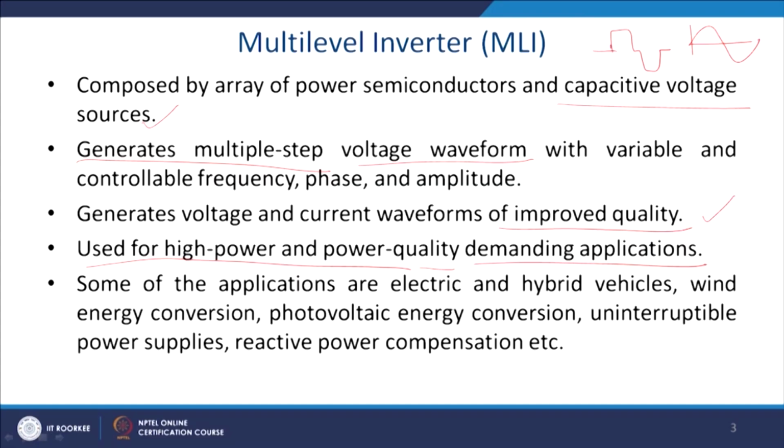But when you are giving this kind of voltage steps, it has a very high dv/dt, and thus the machine's lifespan decreases. We have discussed all those things in the introduction. So, to reduce it, we will be feeding from the multi-level inverter.